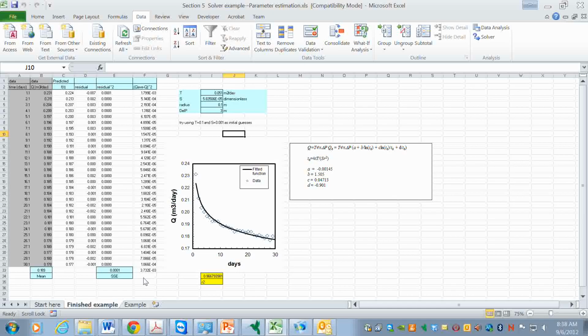I guess really two things. Try these different initial values and see if you're converging to the same value, and try adjusting the initial value to get close. In some cases, for one of the homework problems, you can have combinations of values that are so far off that Solver just really can't advance, and then you get returned the same parameter values that you started with.